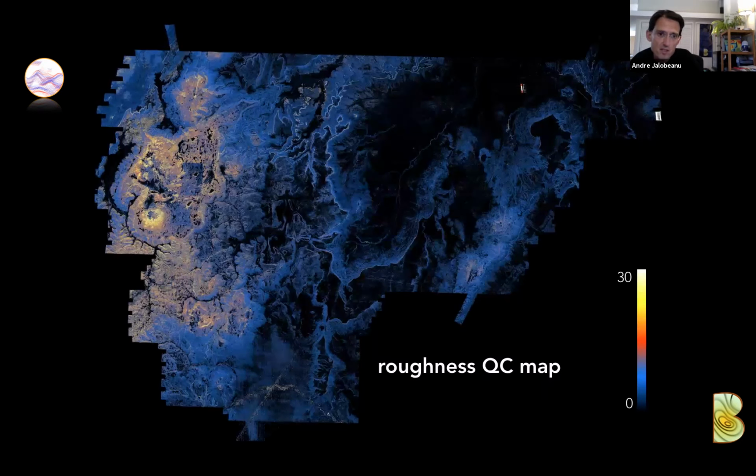The roughness map is nice to look at. It might have some interesting applications. It's mostly intended to show where the areas that are extremely rough are located because they're removed from registration. So if you have 90% forest, there might not be enough information for registration with the current algorithm. So that's the main purpose of this map. It also helps visualize the roughness of the data. For instance, when you have UAV data that's a little bit fuzzy, you can assess that fuzziness by looking at this roughness map and see the improvement before and after alignment.